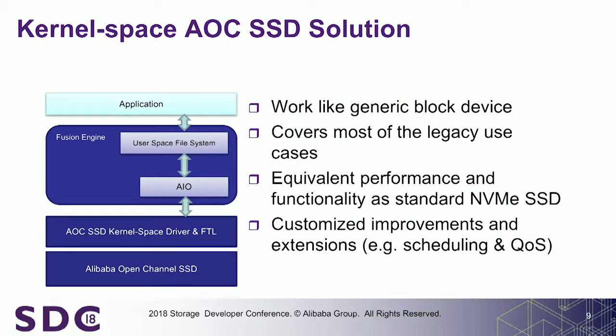So this is the structure for our kernel-space Alibaba Open Channel SSD solutions. We have multi-vendor Open Channel SSD hardware, and of course the firmware. On top of that, we have our kernel mode FTL, which currently is mostly a standard block device FTL. And on top of that, as I said, we do this software and hardware co-optimization, co-design.